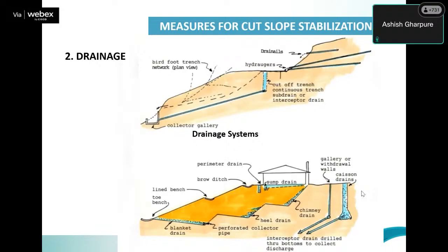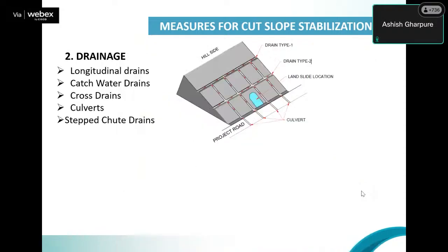So here I'm just showing how elaborate a drainage can be done in a particular hilly environment, because it's not very easy. You have to actually access the water and then take it out. So drain pipes, subsurface drain, French drains, connecting them to surface drains, lots of things that can be done for drainage systems. Next, please.